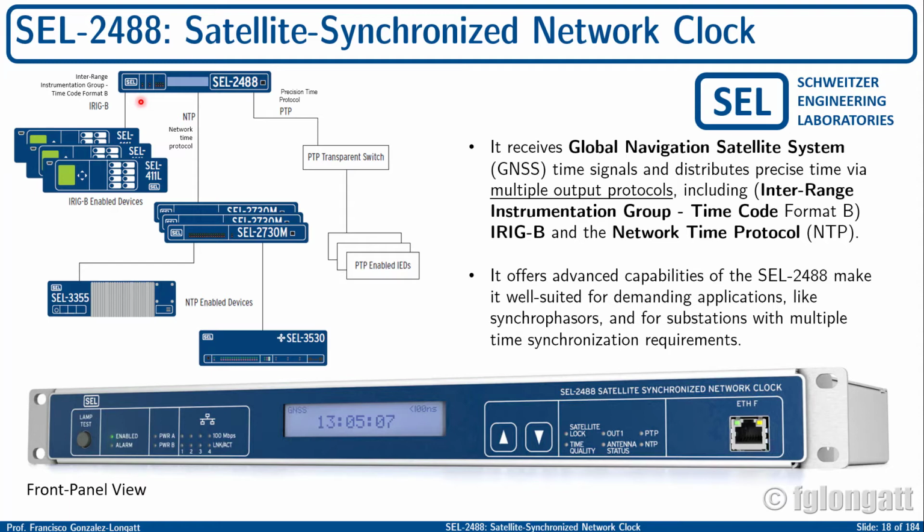This is one of the protocols that can be used directly by SEL products. For instance, in the lab we have the SEL-411L, a differential protection for transmission lines. We will create a video very shortly about this specific type of relay, but what you need to understand here is that if you are interested in synchronized measurements and synchronized trips of those SEL-411L relays, you need synchronization, and this synchronization will be provided by the SEL-2488.